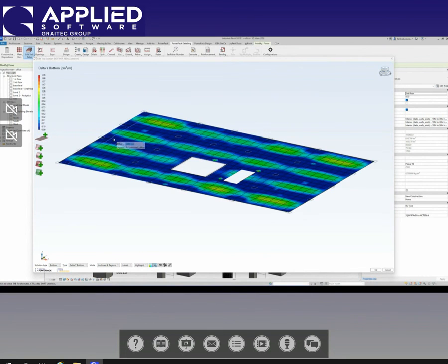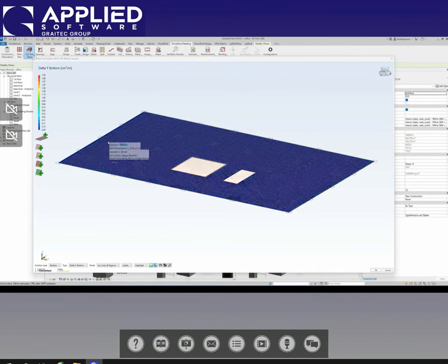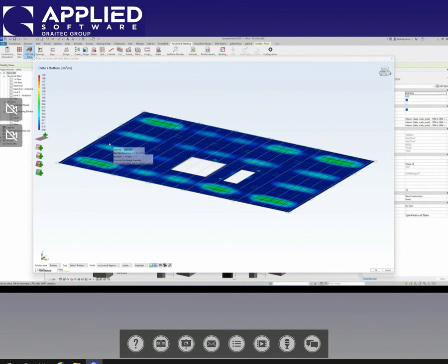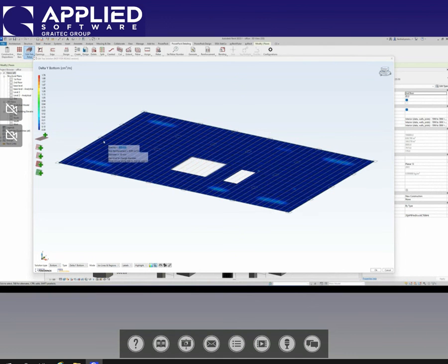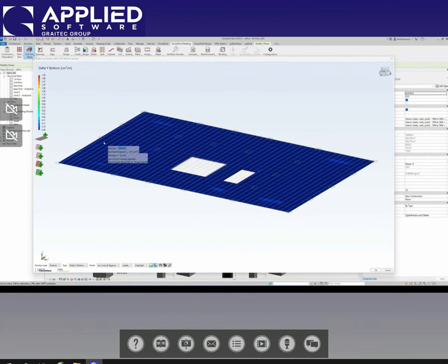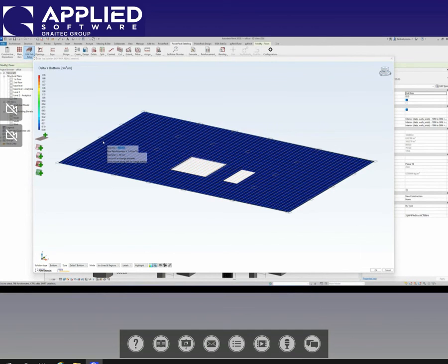So basically, same scenario here. I can start with, let's say, 300 millimeters, and again, based on my finite element rebars, I can put my rebars in a very economical way that I'm not using high value of steel. So that's it. So I'm covering it now. Click OK.